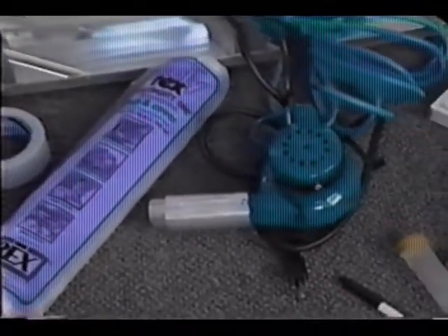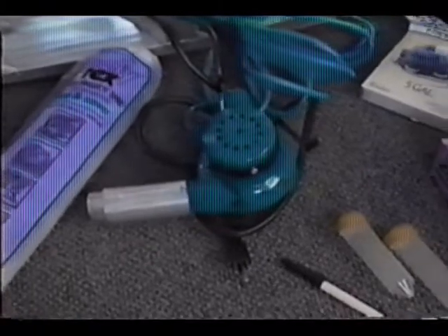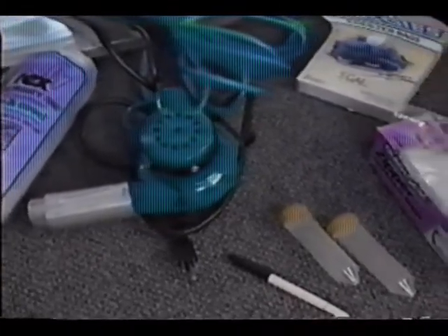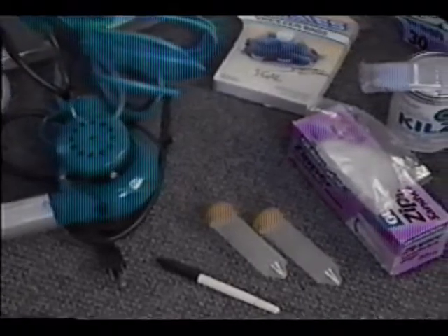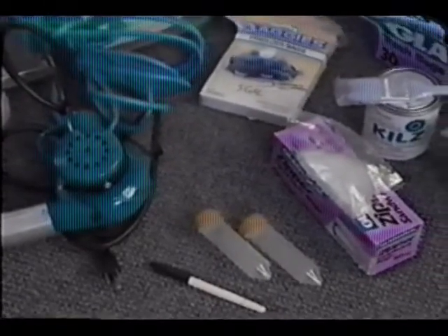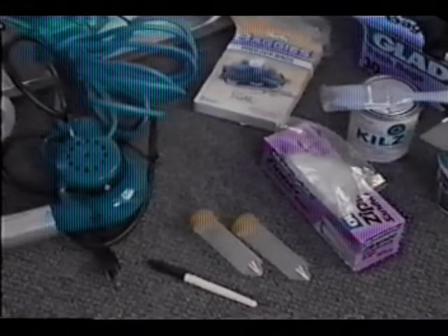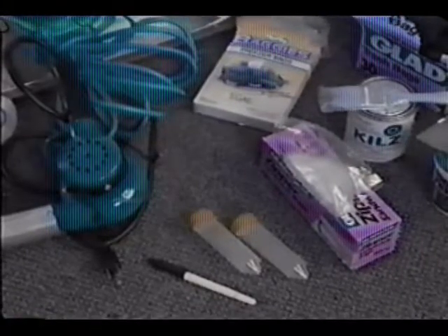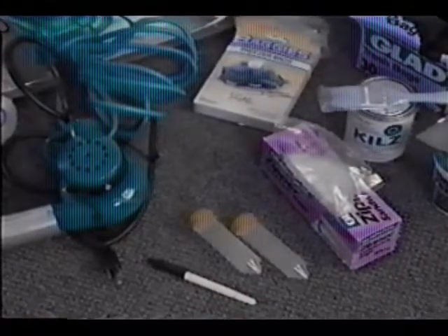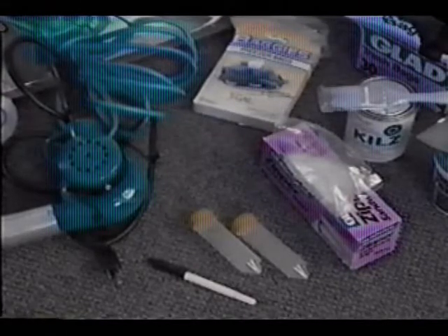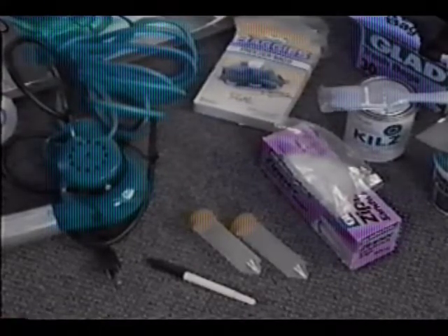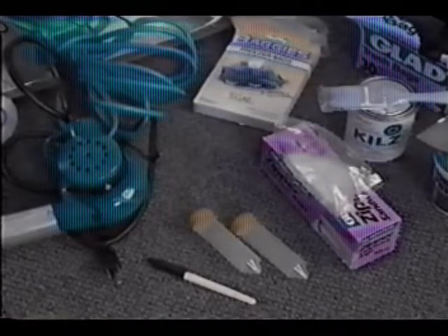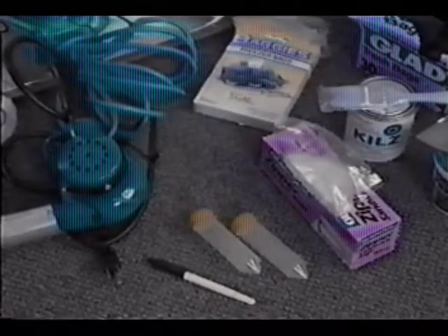The type of container you use to send the chip sample to the laboratory depends on the way the results will be reported. If the results are to be reported in milligrams per square centimeter, use hard-shelled containers that can be rinsed quantitatively to prevent sample loss. If the results are to be reported in parts per million or percent by weight, plastic bags can be used because it's not necessary for the lab to analyze the entire sample.